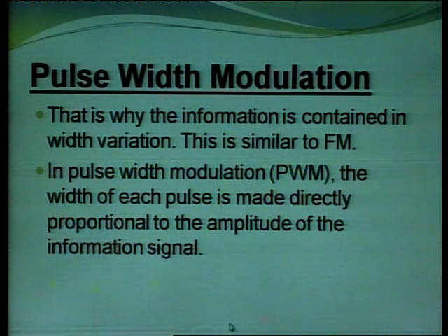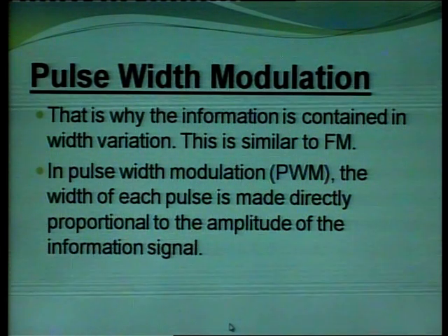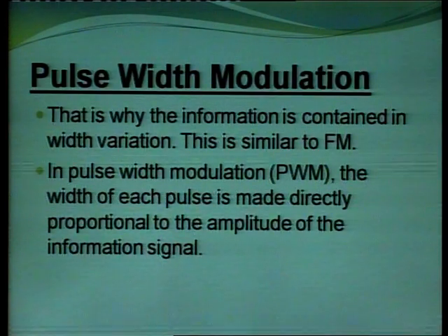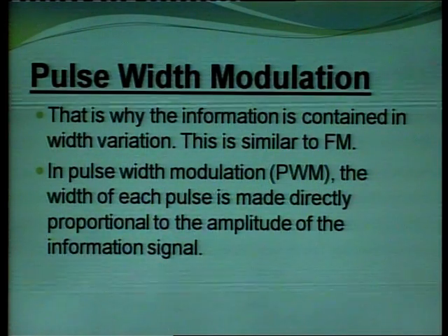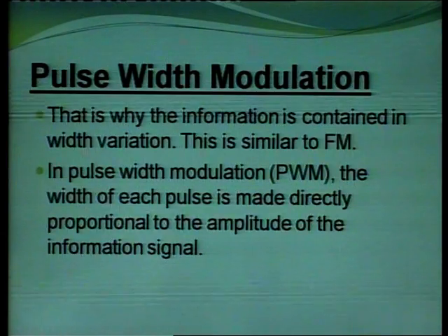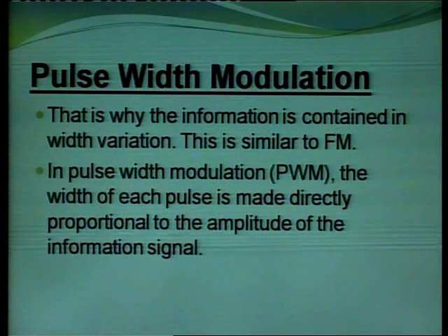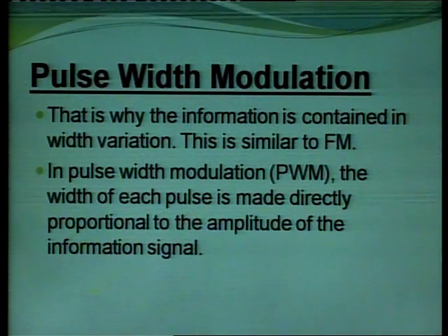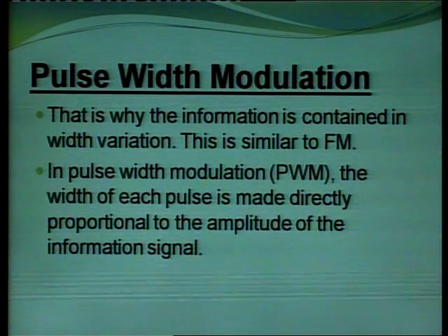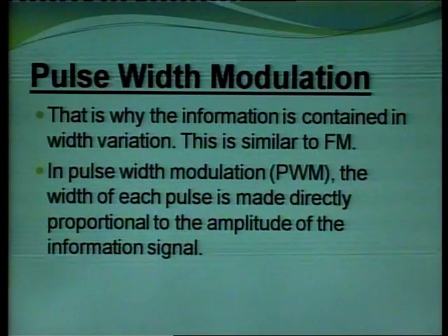So in pulse width modulation, the information is contained in the variation of width. This is similar to frequency modulation. In pulse width modulation, the width of each pulse is made directly proportional to the amplitude of the information modulating signal.